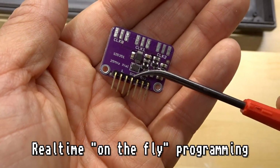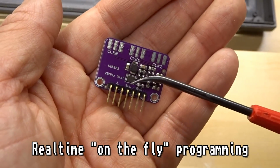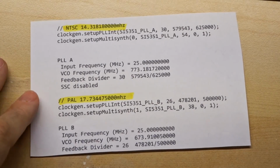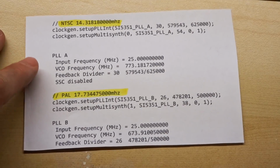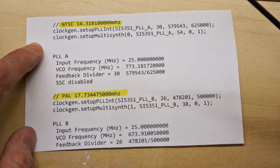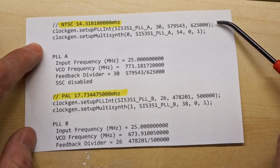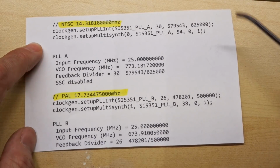And for programming, it just uses a serial line. So there's a serial clock and a serial data line, which will connect to the Arduino for programming. You actually have to use some formulas to program the device to get the exact desired frequency. And I've done that math right here. I'm going to post the Arduino code in the description, and that does all the programming on the fly, but these are the actual two commands that program the device depending on which clock frequency you want.